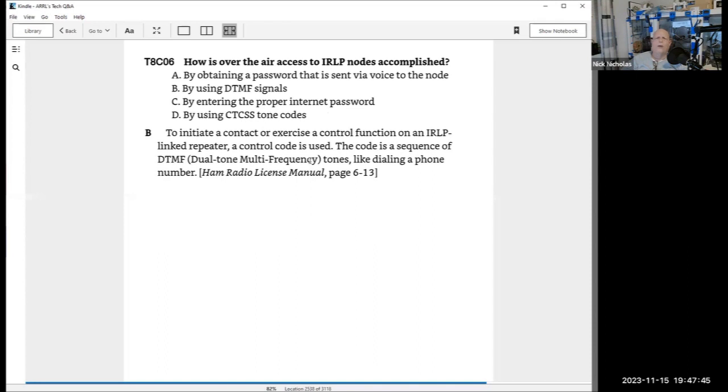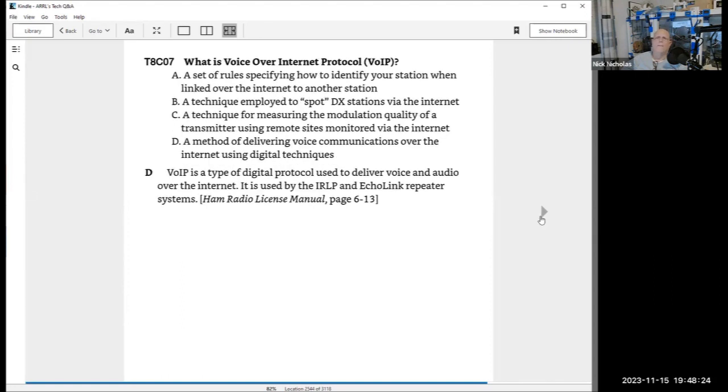So now we use CTCSS tones to bring about our repeaters to activate them in many circumstances. That's a different thing. CTCSS is a sub-audio tone that's constantly transmitted while we're transmitting. It's constantly present in the background. The repeater hears that sub-audio tone and recognizes that it should key up and retransmit that station. The reason for that is to avoid interference. But, okay, I'll move on.